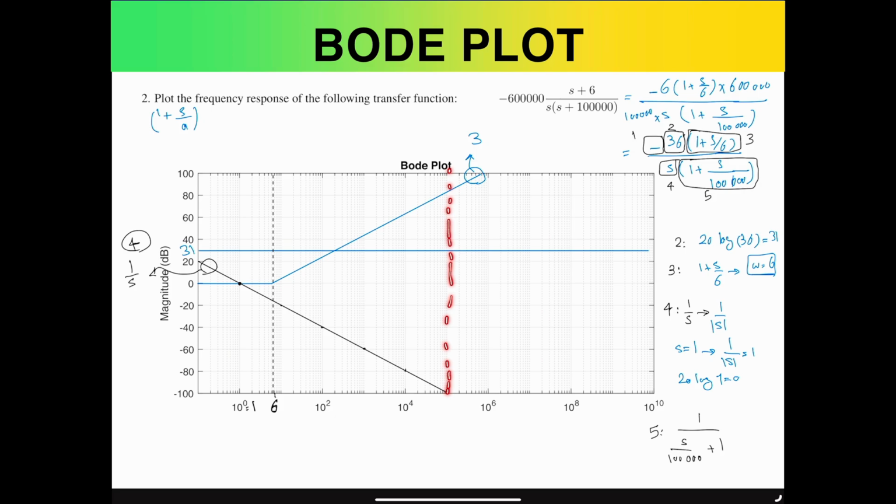And once we identify that, we need to be mindful that all of the lower values in frequency are going to be 0, and higher values are going to be minus 20 dB per decade. So that is the generic form of the pole. So 100k on this line, I'm going to draw that with another color of green in this case, and another 20 dB per decade, which is going to be around somewhat like this. Now, we're done actually on all of the different parts of the question. Let me also call this as this guy, which is number 5.